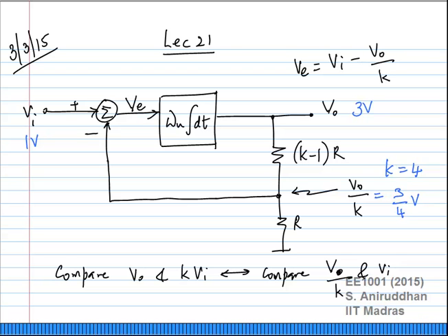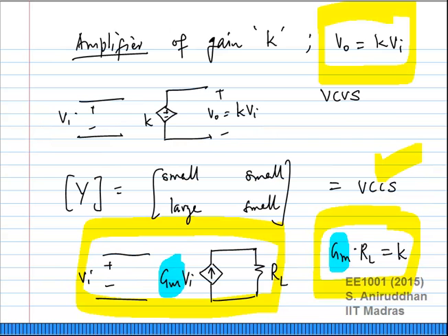This is the generic feedback system for electrical quantities. Correct? Now, some of these things may be composed of control sources. For example, the integrator itself, the driver, the controller, may be composed of nonlinear elements that can be considered to be voltage controlled current sources. But the point is, we cannot rely simply on those control sources alone to generate this value of K.